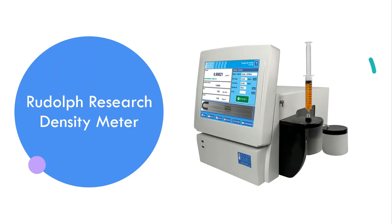First, before I go through that method, what we have in the chemical technology lab currently is a Rudolph Research density meter. So this one's a little bit bulkier, a little bit bigger than the one that you've seen before. But there is a live view on the screen of the density meter, and you can actually watch the sample slowly go into the U-tube, and then it circles around the curve, and then it slingshots and comes all the way back through. So we have to make sure that we fill up that U-tube. If we don't fill the U-tube up, then we're not having the appropriate amount of sample on the inside.